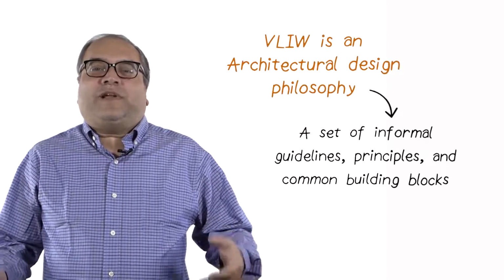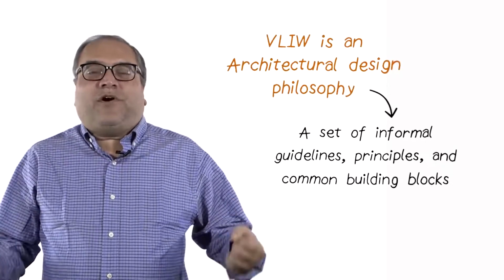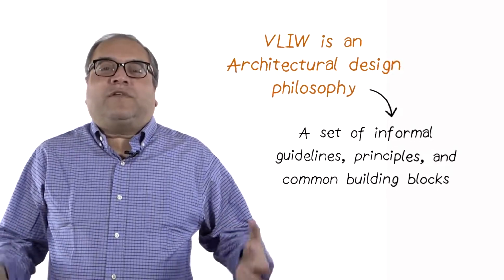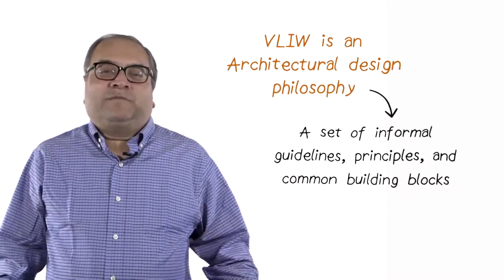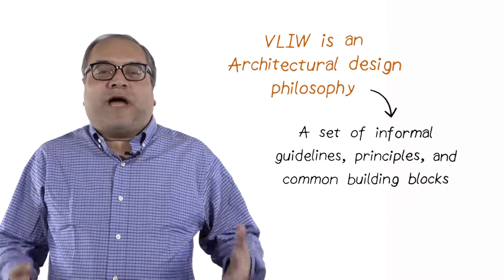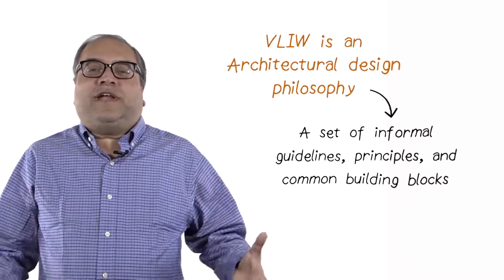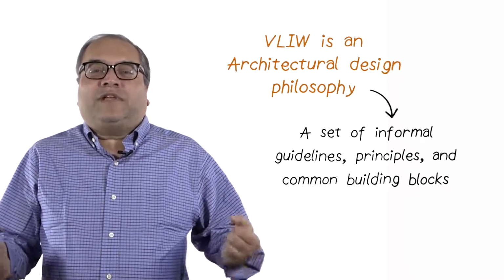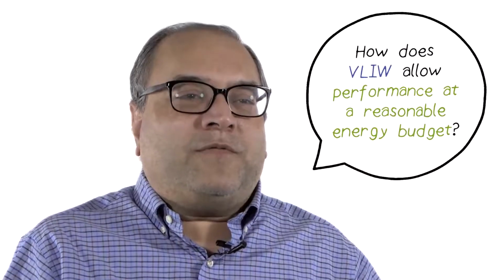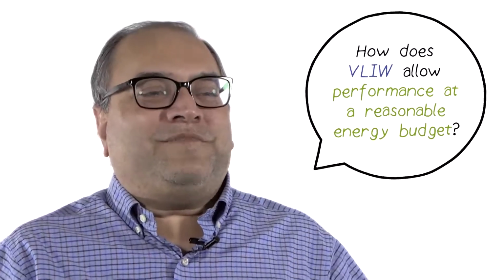It is a set of informal guidelines, principles, and common building blocks that serve as a contract between computer architects and compiler writers. It exposes parallelism to compilers so that the compilers can generate highly efficient parallel instructions called very large instruction words. By the time you have finished this lesson, you will be able to answer the question, how does VLIW allow performance at a reasonable energy budget?